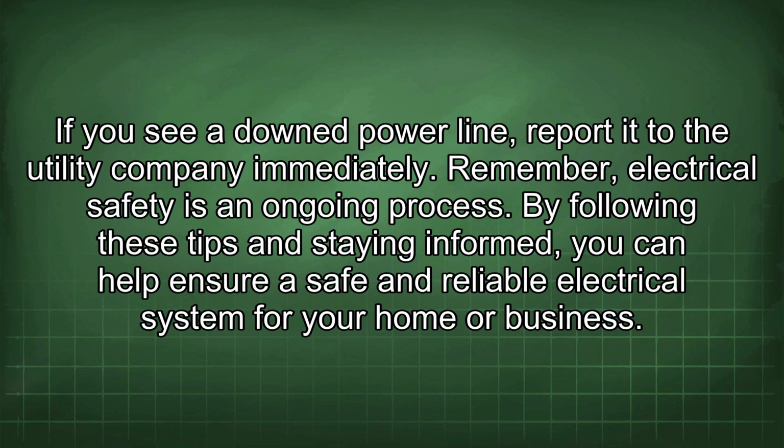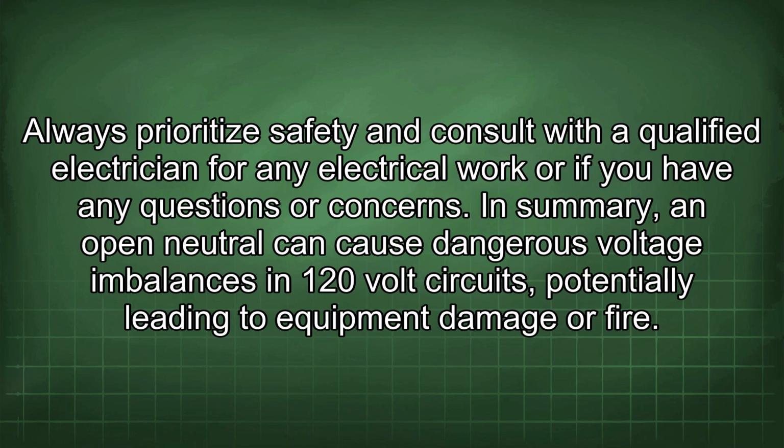By following these tips and staying informed, you can help ensure a safe and reliable electrical system for your home or business. Always prioritize safety and consult with a qualified electrician for any electrical work or if you have any questions or concerns. In summary, an open neutral can cause dangerous voltage imbalances in 120-volt circuits, potentially leading to equipment